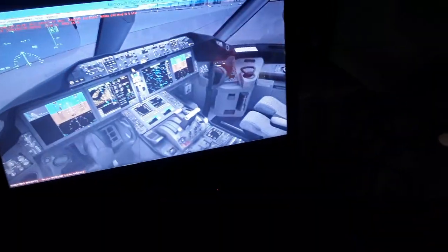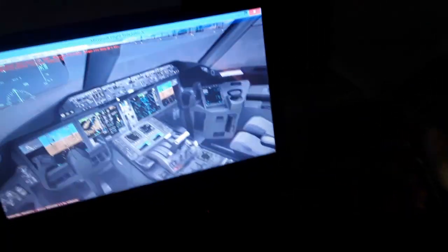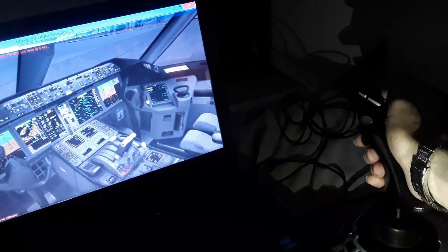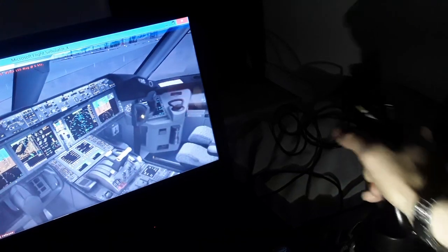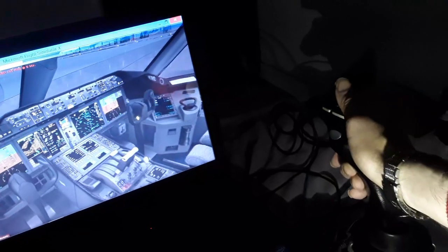I'll show you one more view of the Boeing 787 flight control system. Also, you will see after the flight management computer, I will input all the data we need to make the flight. So I will show you this view of the flight controls right now, and the other one you will see a better view with another screen view, and also you can see the outside view of the flight controls. So you can see also the flight controls are interconnected, they move together. In flight, both the captain and the first officer sides move together, interconnected. Also the rudder pedals. Unless we have a failure in flight, they're not like in the Airbus, where you have the side stick priority button for either left or right side.